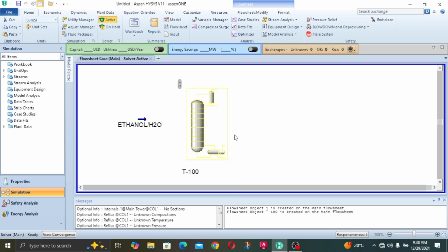But in an event where we add too much heat to the operation and evaporate a lot, a little bit of our water might follow the ethanol to the top, because their boiling points are not that far apart. So we would need to take note of the approach for the operation. It's the reason why we cannot attain 100% separation using a normal distillation operation. We need to go for azeotropic distillation to attain a better result. But for the beginner's journey, like we said, we're going to be sticking with the default, the normal distillation.